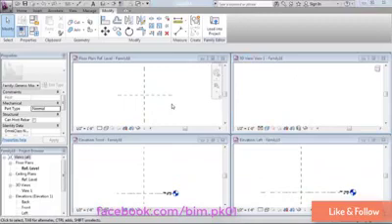So let's go to our fifth and final form, the swept blend. The swept blend is sort of a combination between the sweep and the blend, thus its name. We get two shapes, two sketches, one for the start and one for the end, and then they move along a sketched path. So it's more like a sweep because you get to sketch the path.